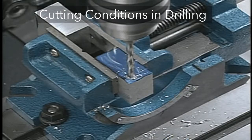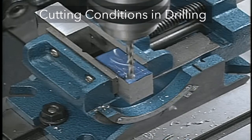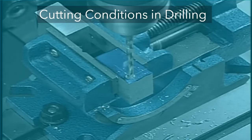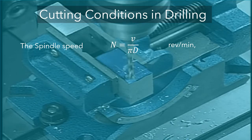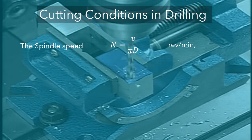The cutting speed in drilling operation is the surface speed at the outside diameter of the drill bit. It is necessary to convert this to the rotational speed of the drill. In this equation, N is the spindle speed in revolutions per minute, V is the cutting speed, and D is the drill diameter.